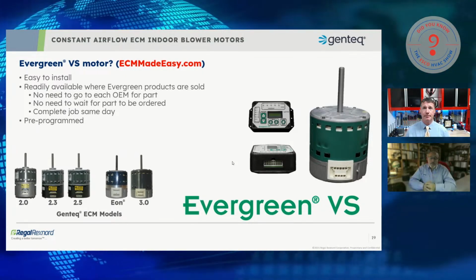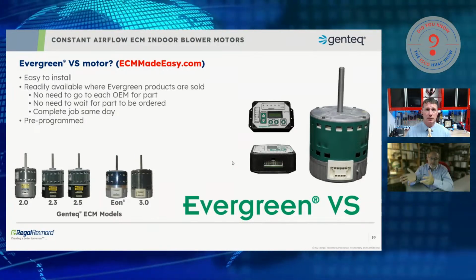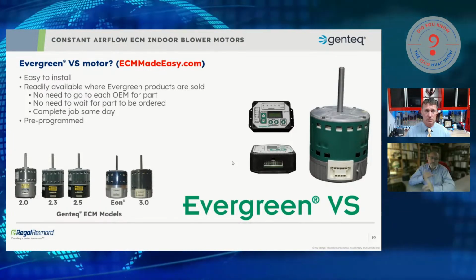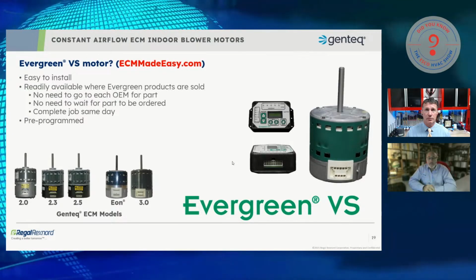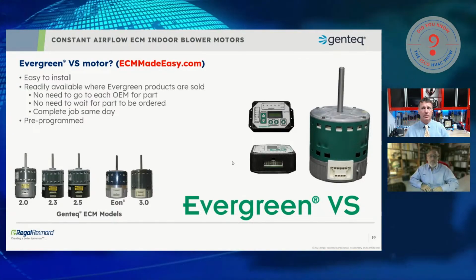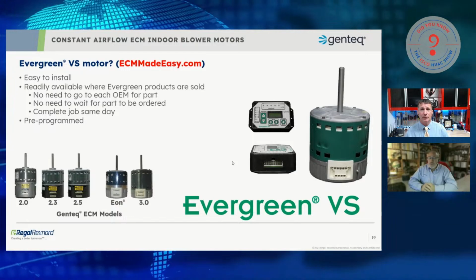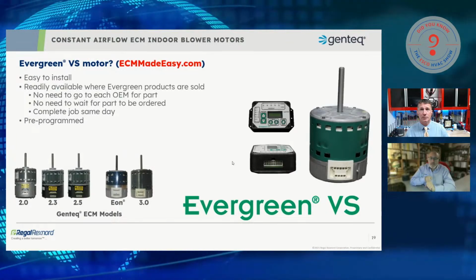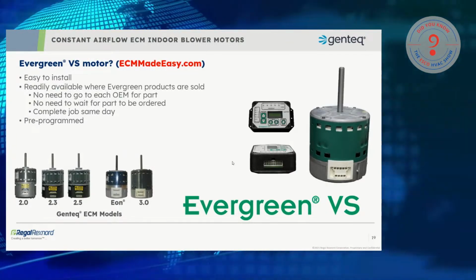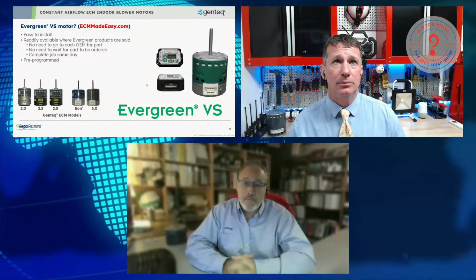So with Evergreen, you can have an off-the-shelf alternative. Will you have to adjust the airflow? Yes. We did set defaults in the UI. We set default airflow for 1st and 2nd stage. We set default on and off delays so that it would be as close as possible. But just like the defaults in the OEM systems, you still need to go in and set the airflow. So I get asked, is it pre-programmed? Yes. Will I have to do some setup? Yes, just like any system. I can't guarantee it's not going to need the airflow tweaked a little bit. But it is going to allow the technician to complete the job the same day.